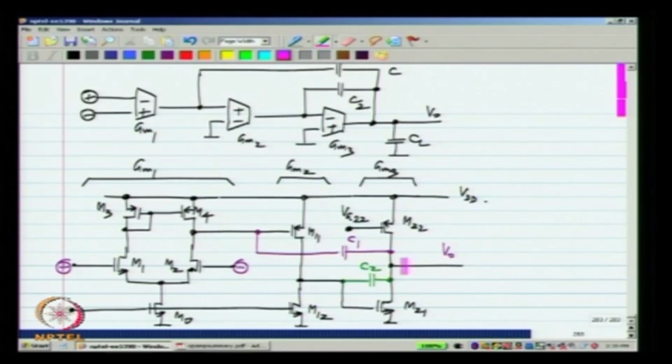transistor M11. Okay. So, now to ensure that may be difficult if you use a real resistor. So, the resistor that you put there has to be matched to the reciprocal of the GM of the transistor M11, and sometimes what you can do is to implement the resistor also as a MOS transistor in triode region, so that the matching across process and temperature corners is good. Similarly, if we want to tailor the zeros in a 3 stage op amp, we can connect resistors in series with C1 or C2 or both.